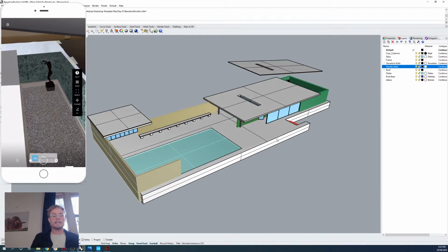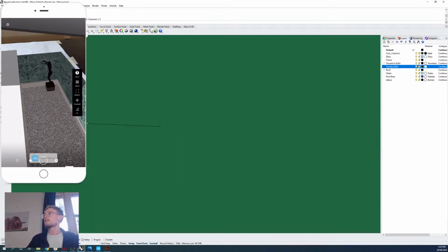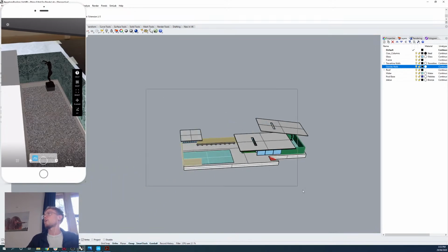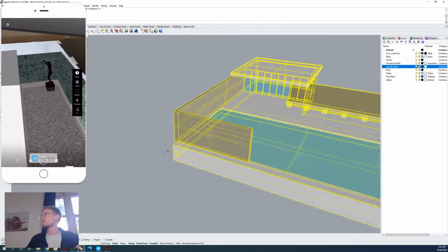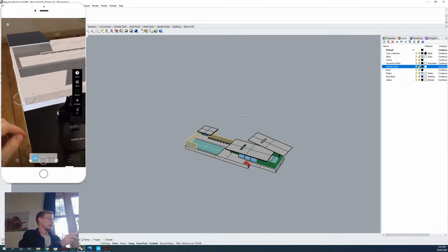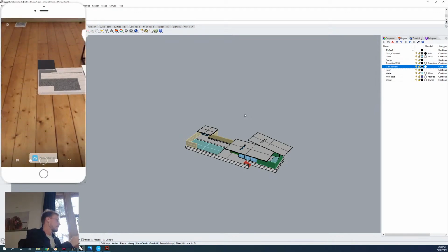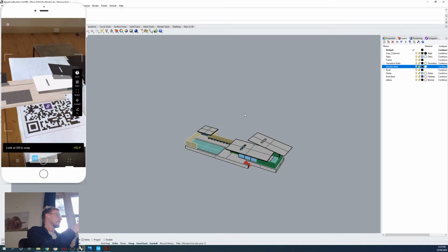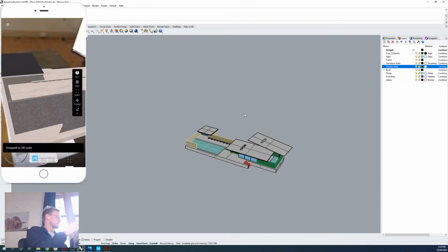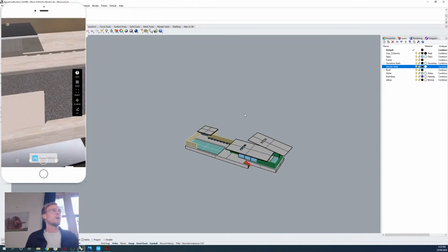As I said before, it creates a model of the origin. If we found the origin point of the Barcelona Pavilion, it's just sitting over here in the middle of it. You might want to align the whole model itself to 0 as well, and then you'll get a more obvious alignment. So you'll see now that it's aligning perfectly to my QR code marker. If I move that onto the ground, there's my QR code marker. I can easily snap that onto my QR code marker just like that. And that's the easiest way to align your AR model to physical space.